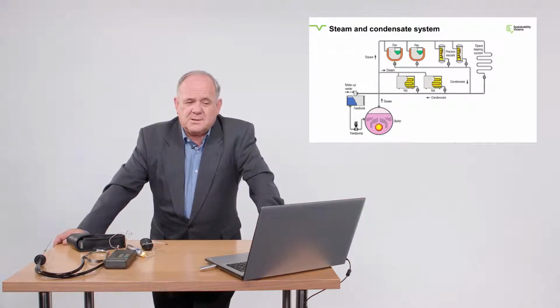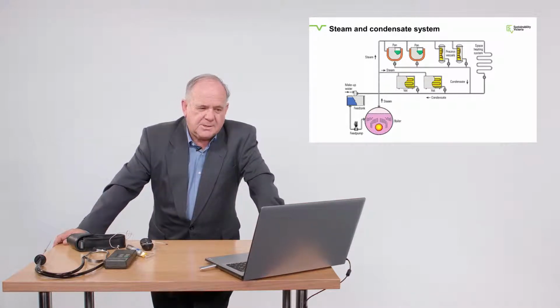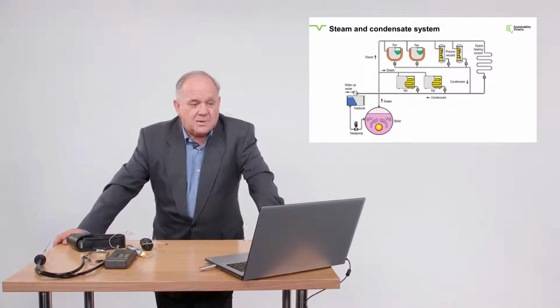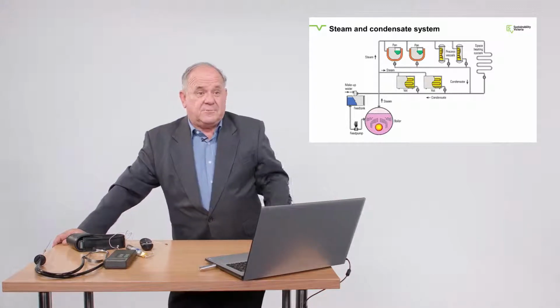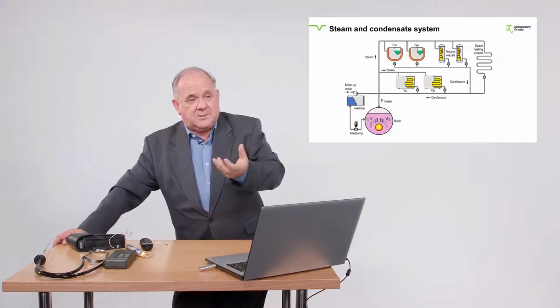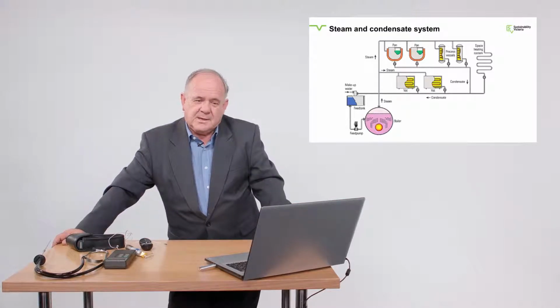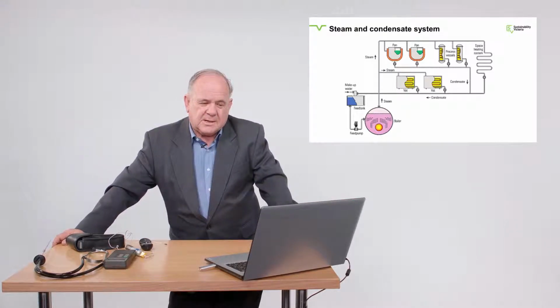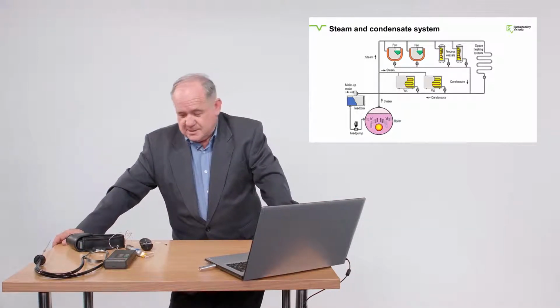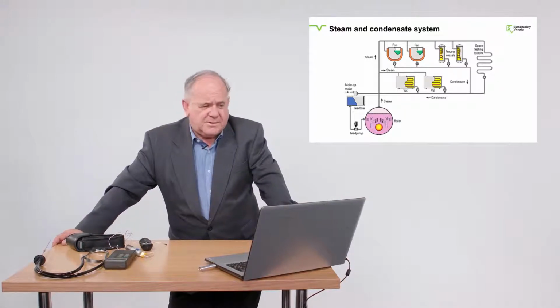So there's all those little things, attention to detail on steam traps, insulation, air venting to make sure there's no air in the pan, for example. If you've got air in there and the steam can't displace it, obviously that impacts its heating performance. So they're all the sorts of things that need to be done in steam trap and steam investigations to make sure that they're efficient.